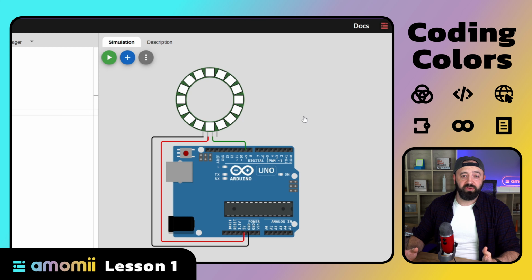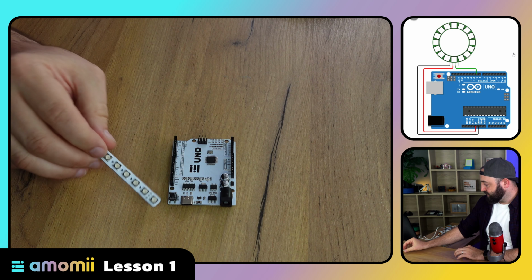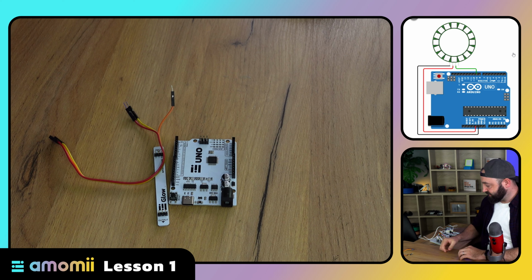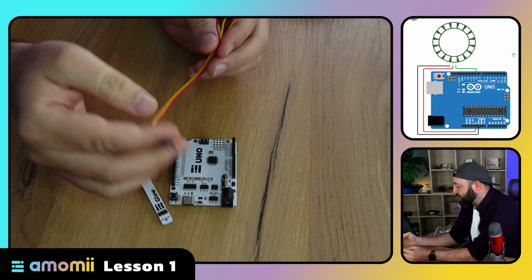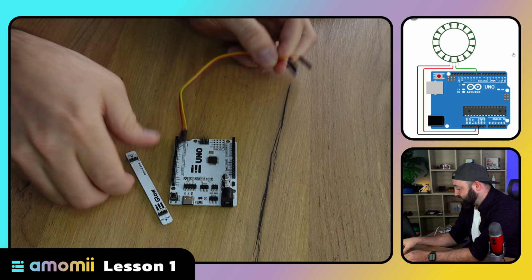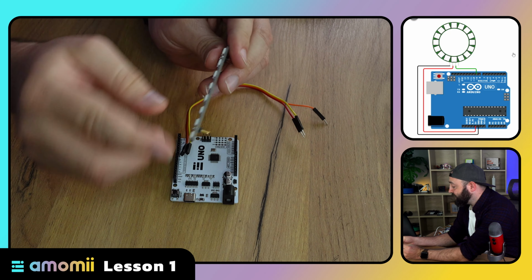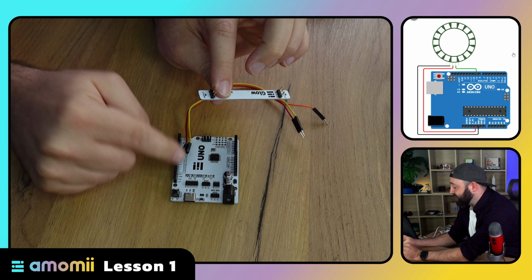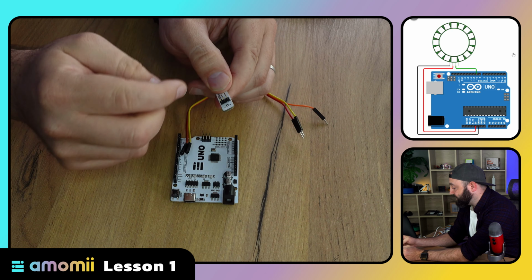Now that we've wired up the virtual version, let's move on and wire up the real one. So we'll need our microcontroller, our LED strip, and some jumper wires. The jumper wires that I will be using have female headers on one end and male headers on the other. I'm only concerned with using one strip, so I only care about the input side, which means information is going to be input into this from the microcontroller. So we just care about these 3 pins.